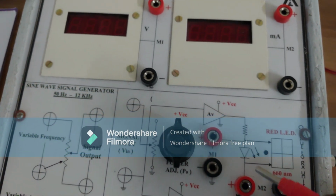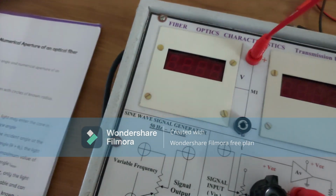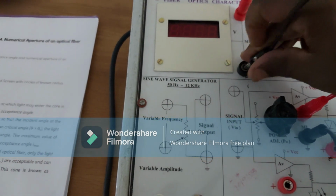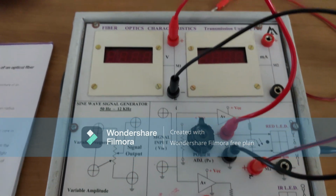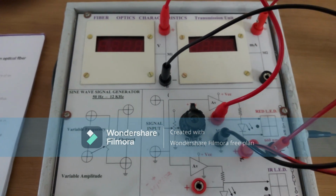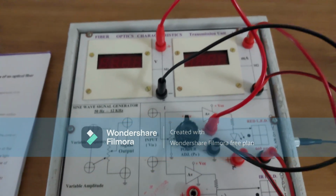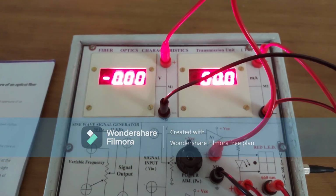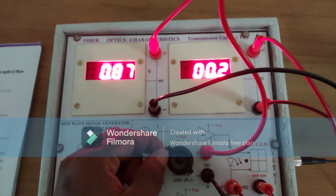Now connect the M1 positive terminal to the voltmeter positive, and M1 negative terminal is connected to the voltmeter negative, and M2 positive terminal is connected to milliammeter positive terminal. M2 negative terminal is connected to the milliammeter negative terminal. Now turn on the power supply. Set the power adjustment to the maximum.